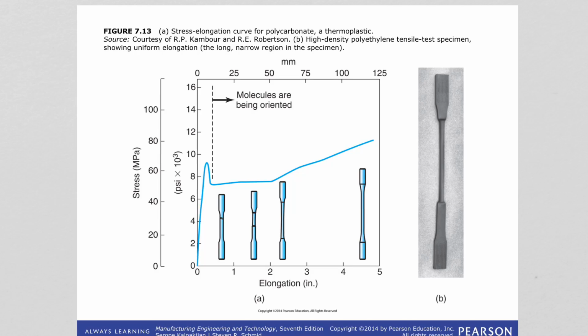Well, just like metals, there is necking during the tensile test. We are seeing a sample for the tensile test of a thermoplastic, and data is recorded, the stress strain curve is given to us, and we can see the necked region of the specimen elongates considerably. But this happens unlike other metals, right? So these materials can undergo large deformations before they actually fracture, and that is what the stress strain curve is showing us.